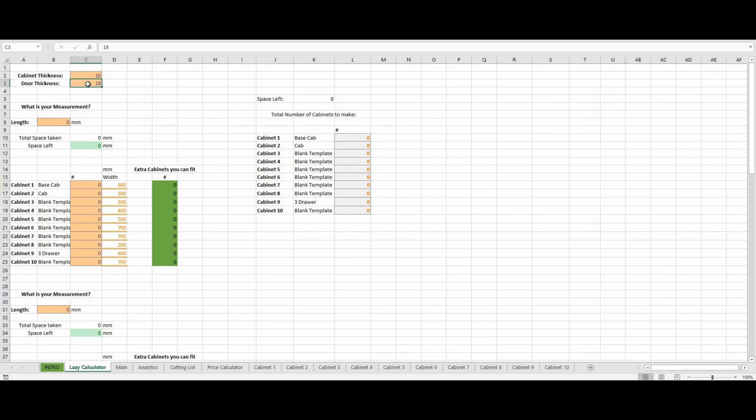After this, we've got the door thickness. A lot of customers have started using 16mm, and I just want to give you guys a heads up. Be careful with your hinge hole drilling, because when you go 14mm deep on 16mm, you end up having only 2mm thickness of the material, and the MDF is very soft, and there are no hinge hole kits standard on the bottom of the machines, or the opposite end of where your hinge hole kit is, and you're going to start digging in. I've had this happen twice already, so just be aware of it. Bottom line, keep the door thickness, your material, ideally 18mm. Unless, of course, you don't have a CNC and you're doing your drilling afterwards, then it's no problem whatsoever.